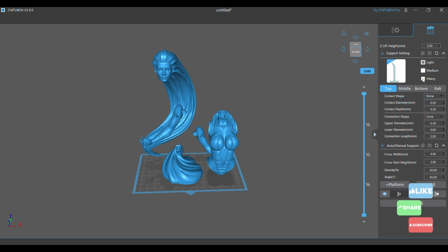As you can see, you can make it all thicker or things like that. The only thing I really do is I click all and I just add the supports, and if there's a dodgy support, I select the support and delete it or edit it here. You can use this to remove all and start again as well, so let's just do that.